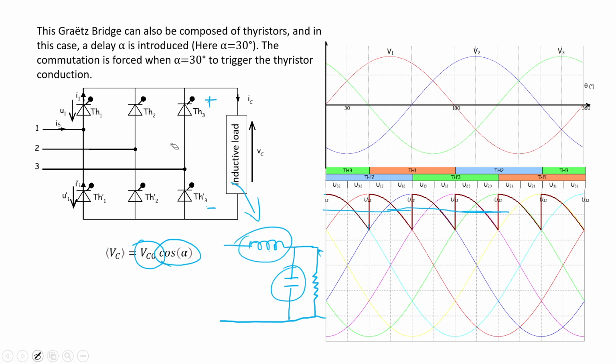If you use MOSFET and only a capacitor, it can destroy the MOSFET. It's the destructive circuit you have learned before actually. If you don't use this one, you only have this, you might have a destructive circuit. So the best way is to use both inductor and capacitor to protect all components.